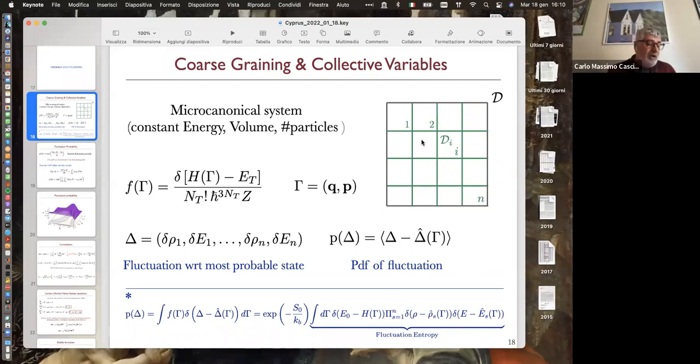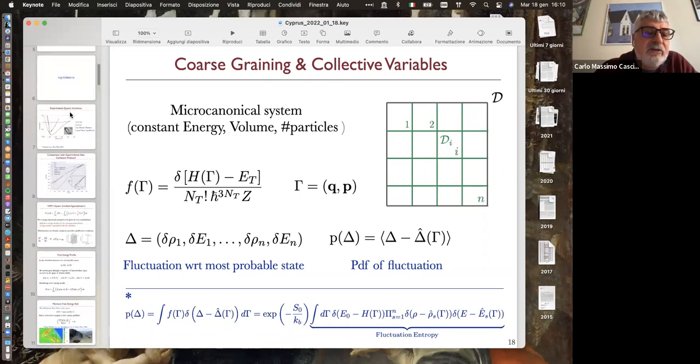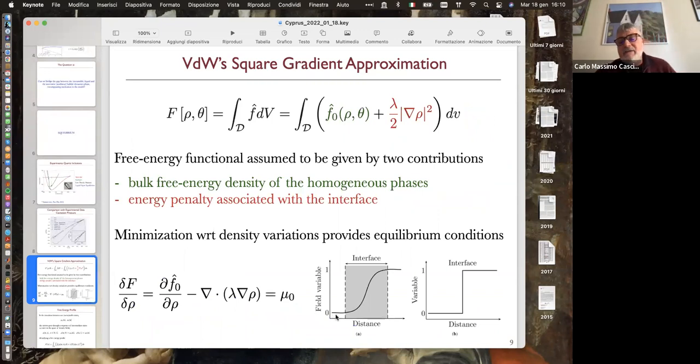Okay. So what happens basically is that first of all, you have to fix a grid size that you think is sufficient. In particular, for us, the criterion is based on the thickness of this diffuse interface layer over here. In this slide, what you see pictured is the transition from the vapor to the liquid across the interface. So this interface has a certain thickness, and that thickness is a physical thickness. So it's not a free parameter.